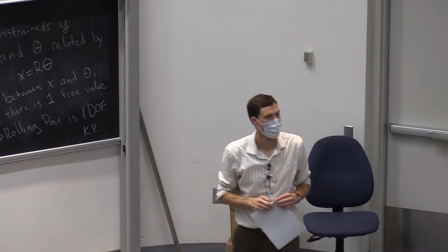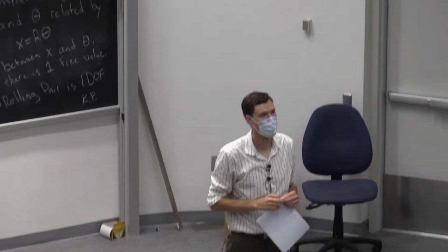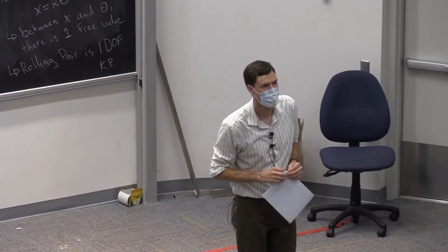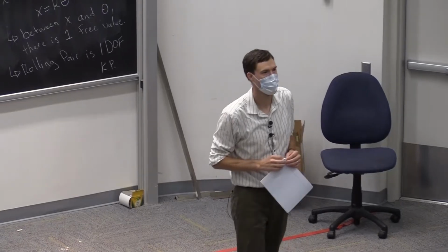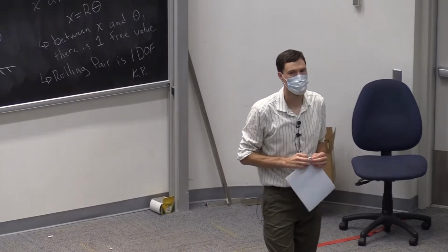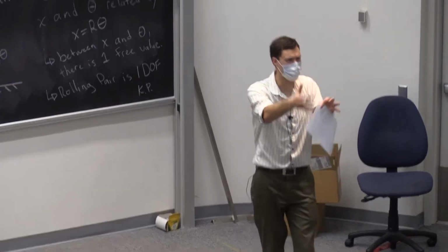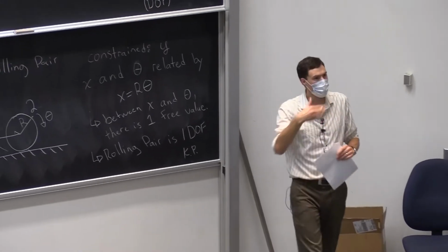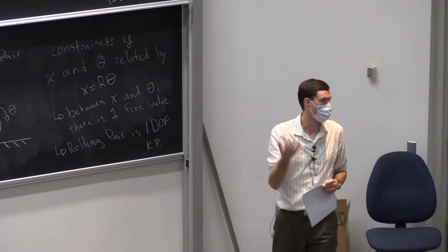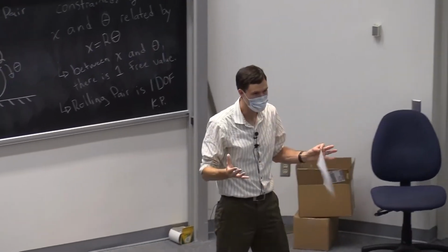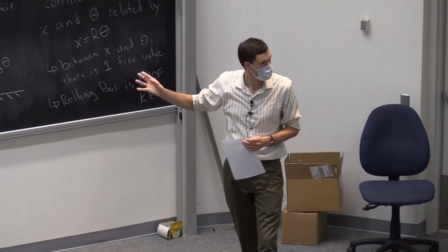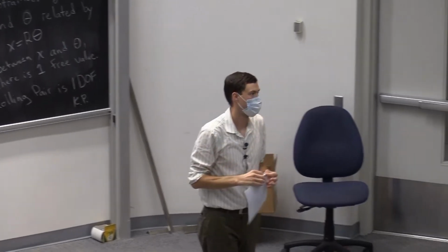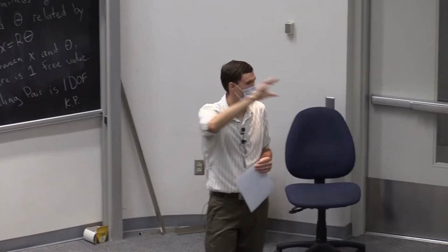Yeah. So when I choose that one of them is free, is the choice arbitrary, or is there a specific one that I'm supposed to hold? And if so, the case that there's one that I'm going to hold specifically, which case would that be? Is it gears, or is there a specification? Yeah, so the question was which one is free, which one do I hold, and it's arbitrary, it's up to you. And where we're going with all of this is towards calculating mobility, which is going to tell us for an entire mechanism, once we look at how many links and how they're connected with these different types of kinematic pairs, how many different inputs are there for the whole mechanism? And it's not going to tell us which input is where, right?